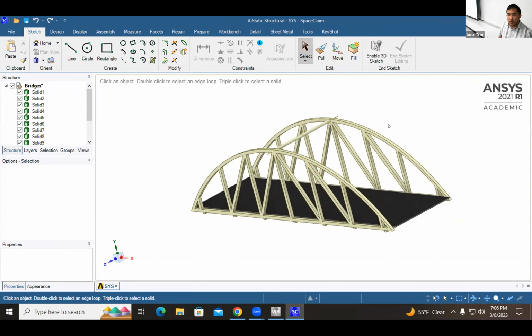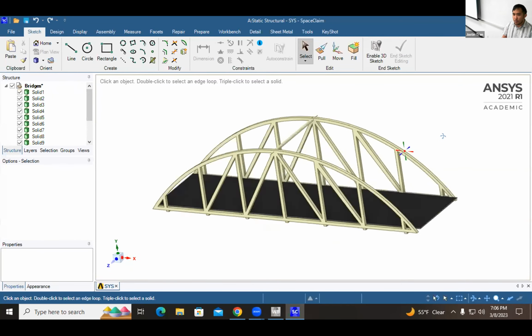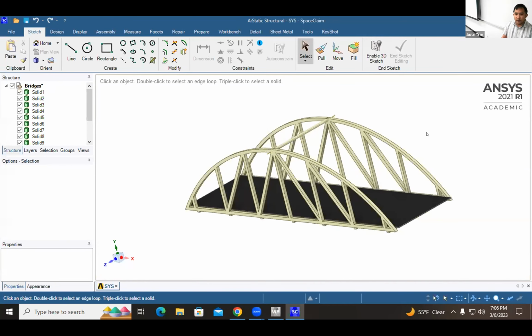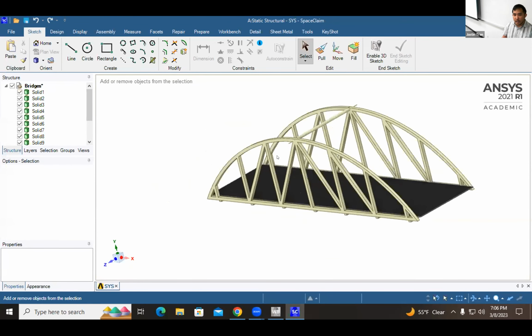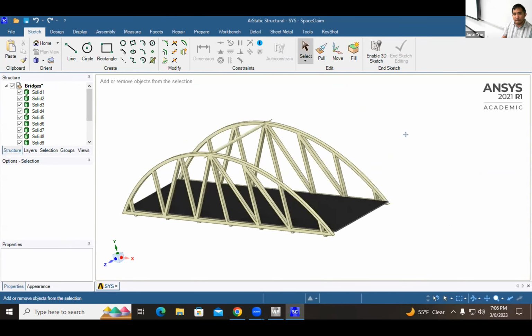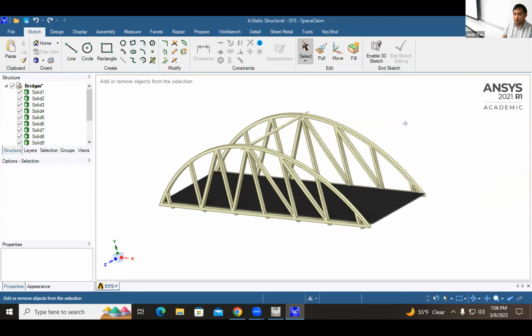Okay. All right, so just a quick primer on the mouse controls here because it's going to be useful. To rotate the geometry, I like to click down on the center button. If you have a mouse, just click down on the center button and you can rotate the geometry. If you want to pan, and so drag the camera left and right, the way I usually do is I hold Control on my keyboard, and then I click on the middle mouse button and move it left and right, and that pans the geometry left and right as well.